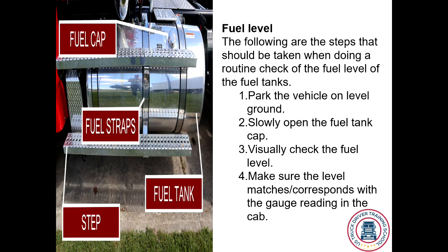Fuel level. The following are the steps that should be taken when doing a routine check of the fuel level of the fuel tanks. Park on level ground. Slowly open the fuel tank cap. Visually check the fuel level. Make sure that the level matches or corresponds with the gauge reading in the cab.